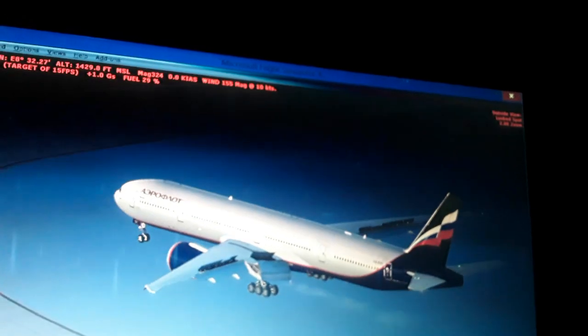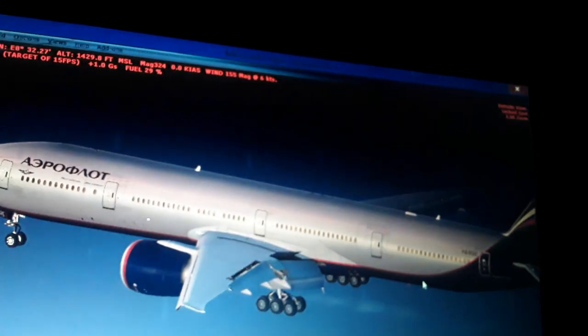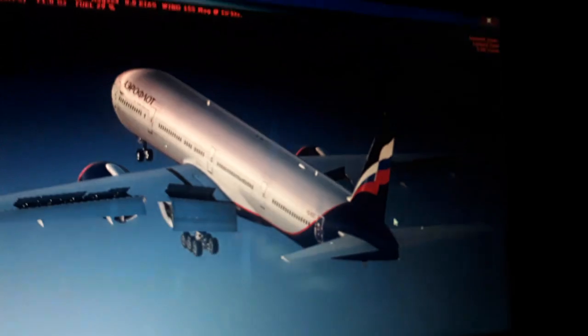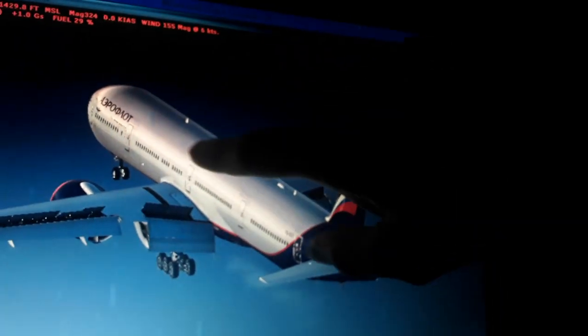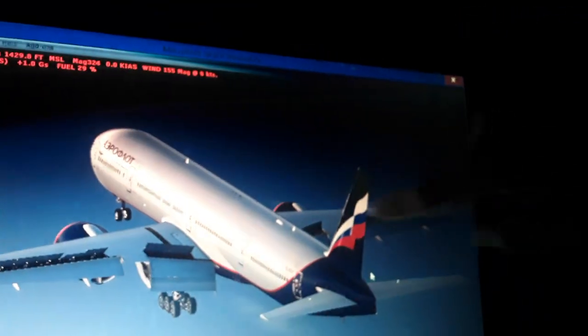So I will show you now other forces, like the deflection of the airflow using the ailerons and the spoilers, that create the lever arm, the moment arm, on the wings that make the aircraft bank left and right. Also pitch up using the horizontal and vertical tail. So the moment arm or the lever arm is times the distance from the center of gravity all the way back to the horizontal or the vertical tail, or from the center of gravity to the left and the right